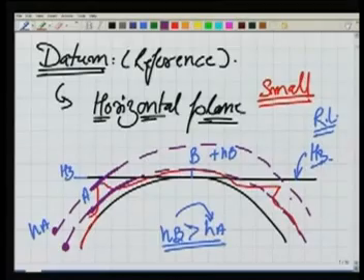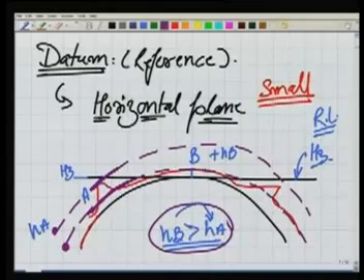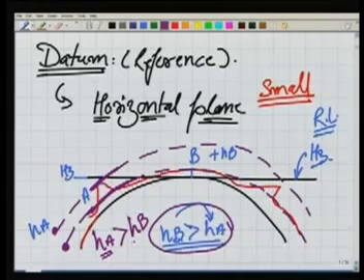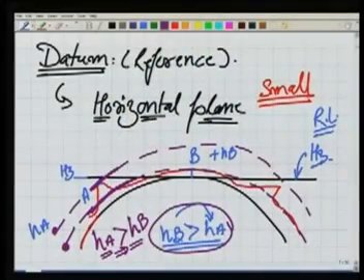If I take the horizontal surface as my reference, it is giving me the wrong result. The actual result should be that HA should be higher than HB, and then only the water from A will flow towards B, as is true in terms of the gravity also. Now from this diagram, one thing becomes very clear to us, that if our area is large, as we have seen also here, we cannot take the horizontal surface as the reference surface.